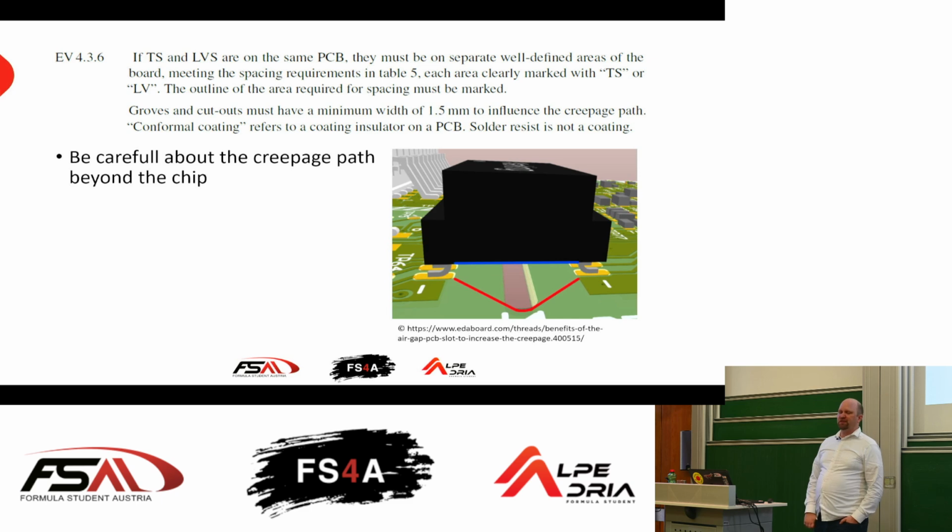We also changed the clearance and creepage rule a little bit. For the clearance, to have a better clearance, you can now cut your PCB, but always be careful.